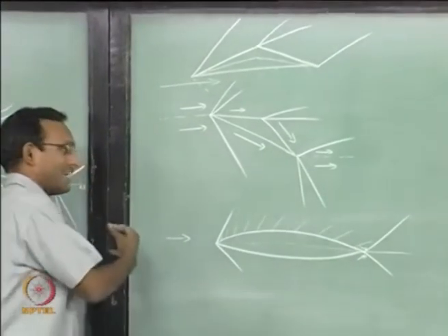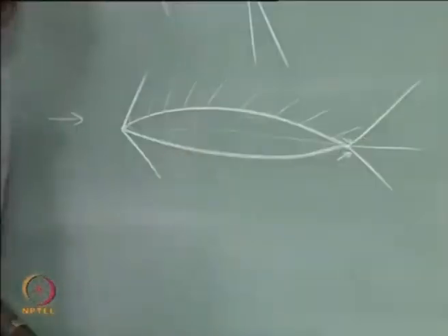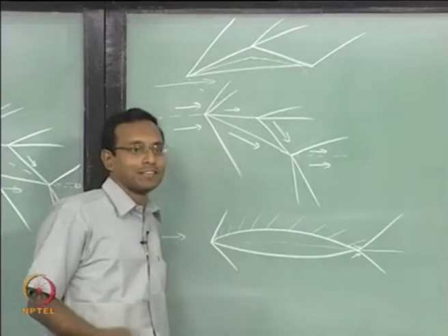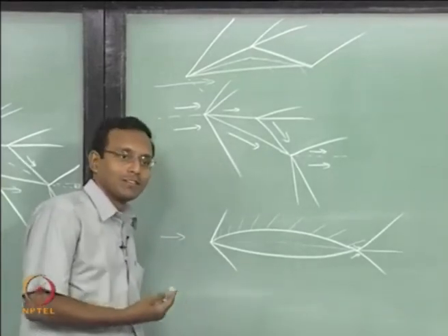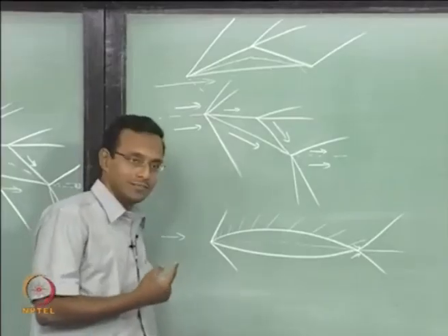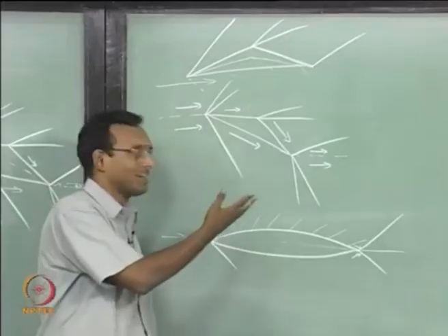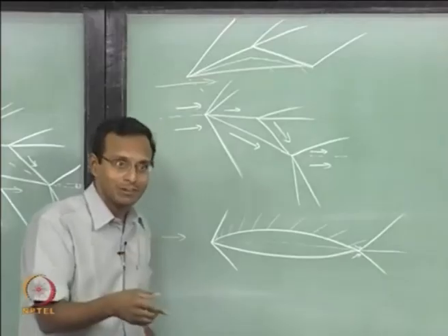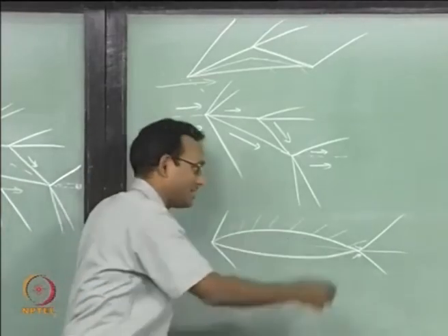This is all again shock expansion theory, can give you pressure data all around the airfoil. This is why high speed flows, aerodynamics people use shock expansion theory a lot. This is application of gas dynamics directly there. So if I have any high speed flow around a body, I can immediately use shock expansion theory to give pressure around the body always, which means I can, whatever we just did, lift coefficient, drag coefficient, I can give you moments on the airfoil, I can give you all kinds of data like that. I can tell you what are all the features I will see.